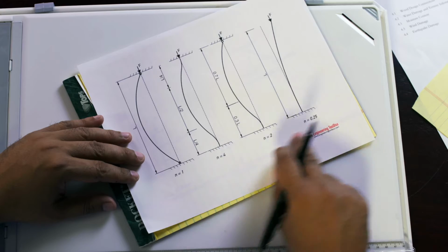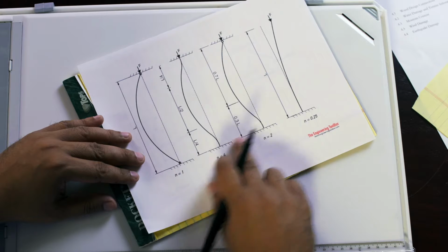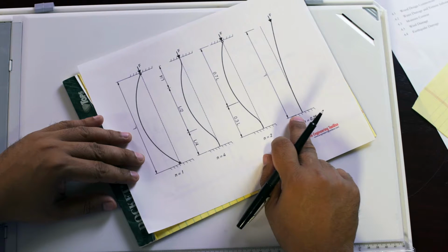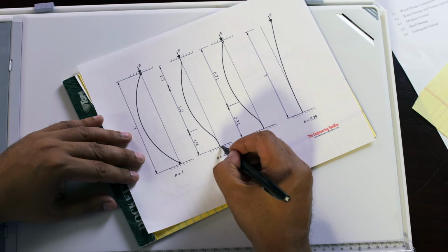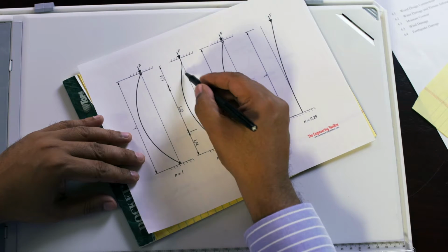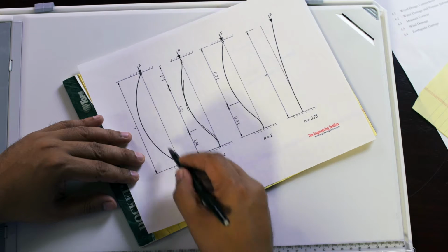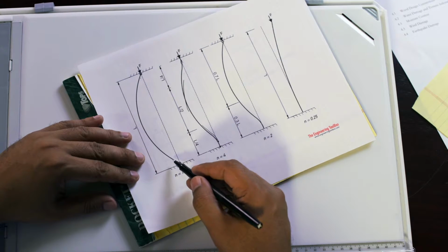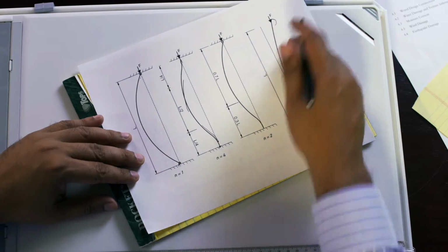This is illustrated by a very nice sketch here that I have, which tells me for different types of end fixities what happens with different types of columns. So a slender column which has its rotation fixed at two ends will develop a buckling curve that looks like this. If it's pinned at two ends, it'll develop this type of buckling curve. If it's not fixed at one end, it'll have this type of buckling curve.